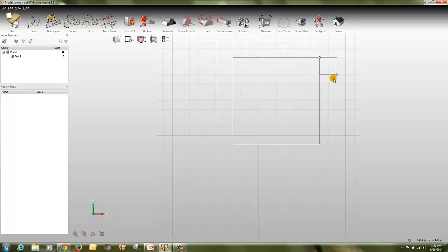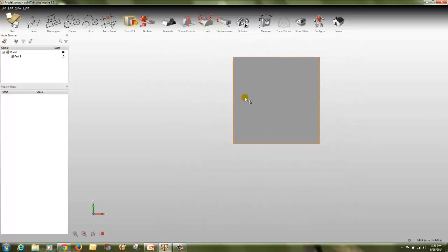So now I can change this. You can see I can change it as I want. These are the parallel lines. You can also move the lines up and down. Say 100, 100. So this becomes 100 by 100 again. So just click on the line. You can have it as you want it. Again, right click to exit. So this will become a face.